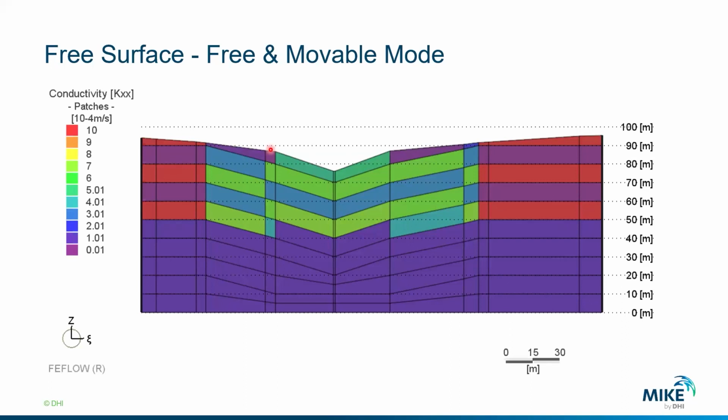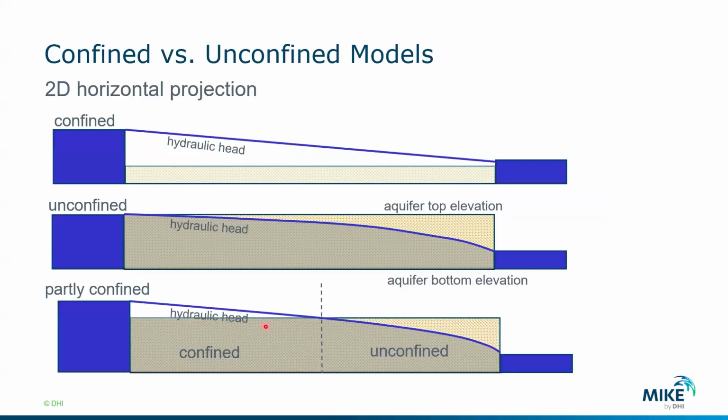The second is if you have very heterogeneous systems, you wouldn't like to go for this method because it's going to average some of these properties and it's going to represent not really what you want to model. If you have multi-layer wells, these are special boundary conditions for 3D models. Your multi-layer well will also change in length, so you need to be careful with this. So you need to really evaluate whether this method fits or not for your parameters.